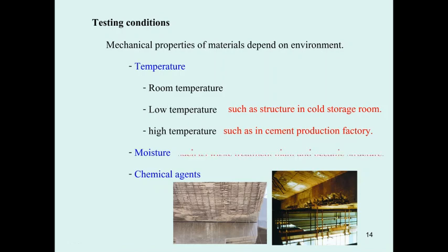Okay, next, talking about the moisture. The moisture has a bad effect on the steel, even when the steel is put in the concrete. The concrete can protect steel somewhat, but not totally. Because when the water reaches the steel, it will react with the steel and get rusted.